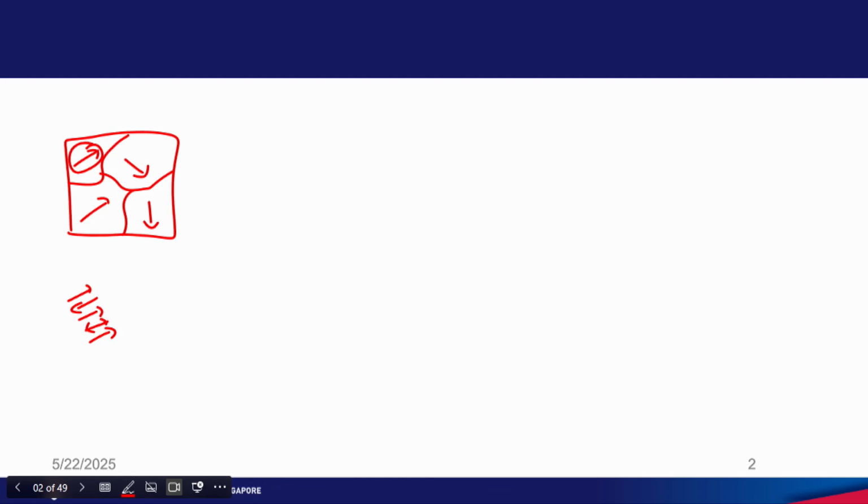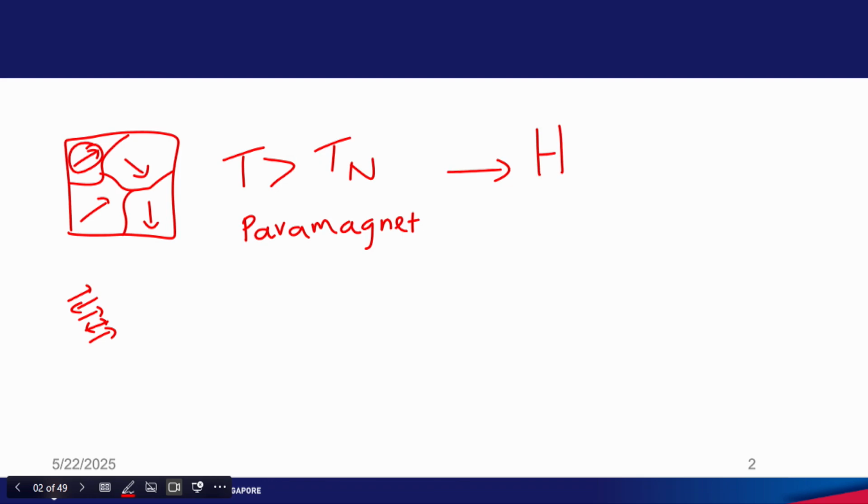During the annealing process, you apply a high temperature, more than the anneal temperature. Thereby you make the antiferromagnetic material a paramagnet. At this point of time, you apply a certain magnetic field. This magnetic field forces the magnetization of the ferromagnetic layer on top to be along a certain direction.